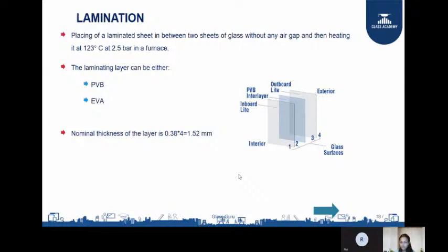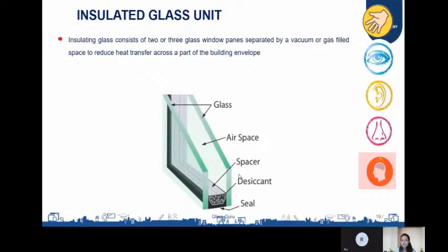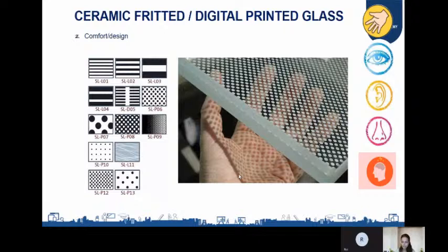First we have the toughened glass. So toughened glass is what? It's a process of improving the material characteristics by heating to a high temperature. When you have the raw glass, you again put it in the furnace, you again heat the glass and again you cool it down, right? When you do the cooling, it will be very sudden cooling, and because of the temperature difference and the difference in stress, you can get a stronger material.